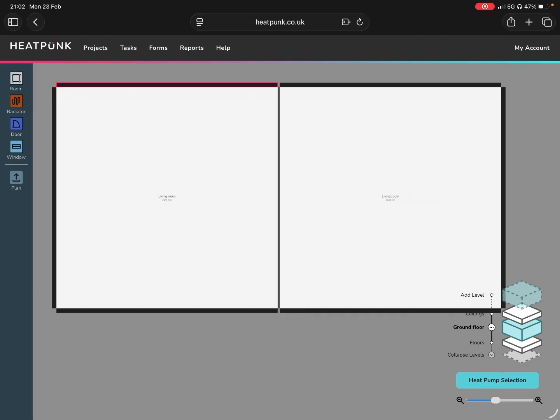They're often rated or named based on their outputs at an average outside temperature for an average climate, which is somewhere around 7 to 10 degrees air temperature. And that's what they'll be showing their output at as a 35-degree flow.